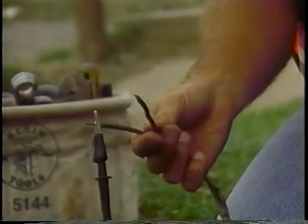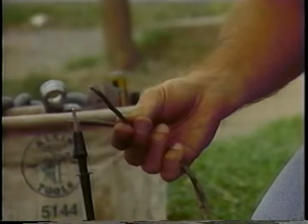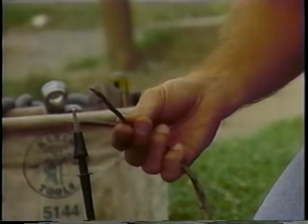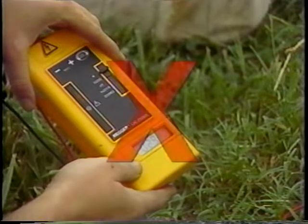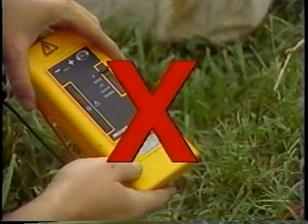To ensure that there are no breaks in the probes or wire insulation, you should also check that the resistance to ground value is high. Do not, however, use a megger to check this resistance because the high induced voltage will destroy the probe.